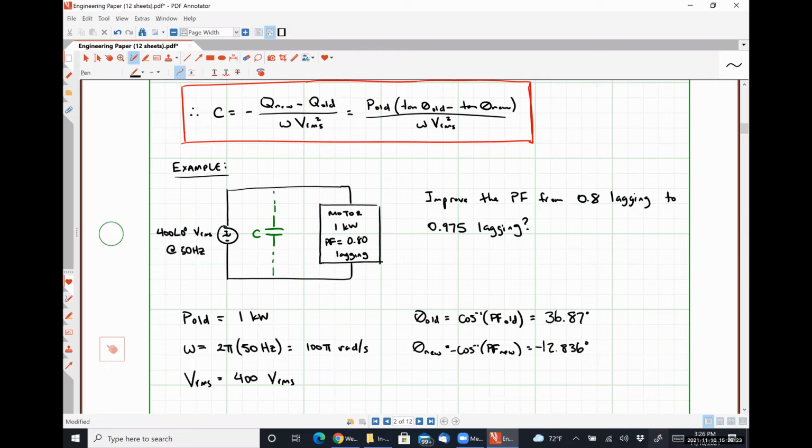Whenever we have a negative power factor angle, we have a leading power factor. Whenever we have a positive power factor angle, we have a lagging power factor. Always, always, always. So anytime we are trying to hit a leading power factor, we are forcing that power factor angle to assume a negative value. And we accomplish that by overshooting, which is what Ian mentioned.